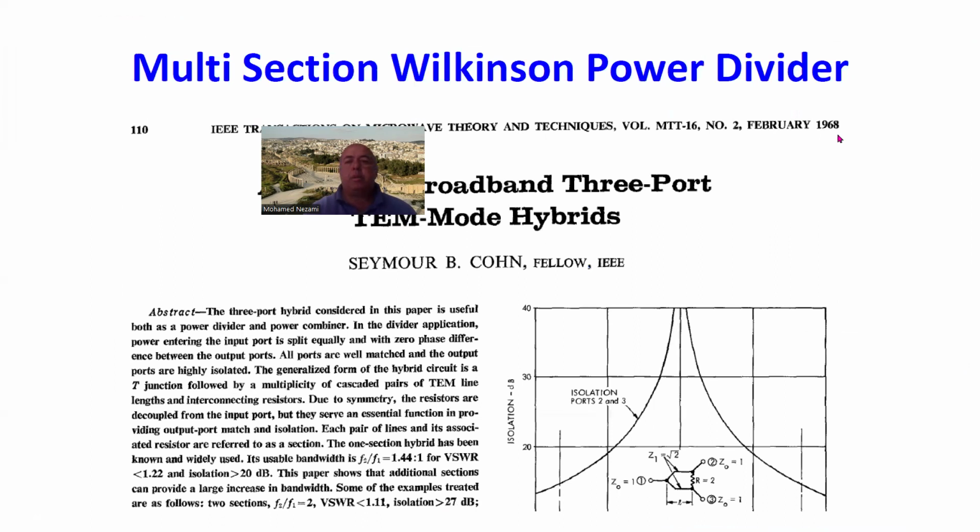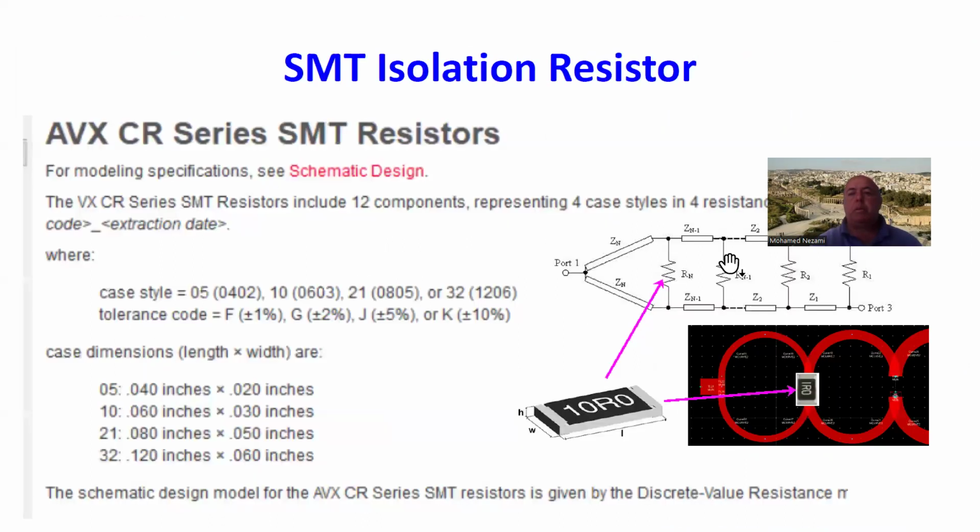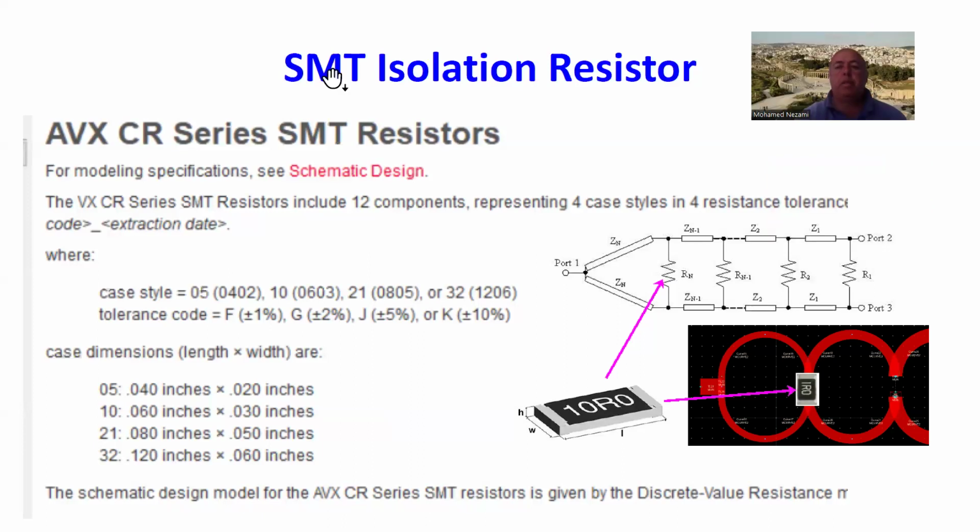So now that's basically some of the technical background. The layout: when you start out a design, what you end up with is a bunch of quarter wave lines in here. But really, you have to transform this into an artwork like this because that's what you really need. You need a curved or semicircle based design so you can have spacing for the surface mount resistors, okay?